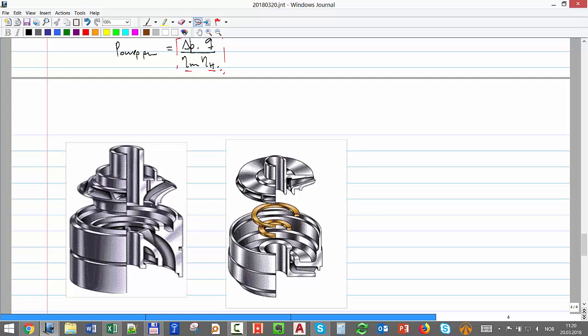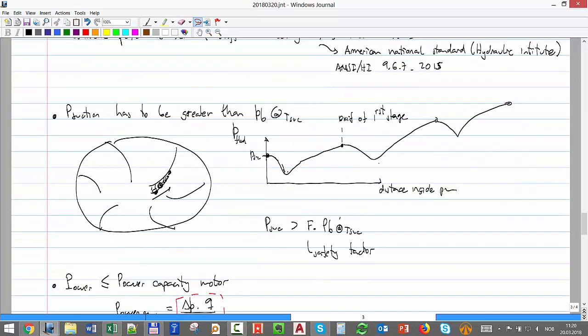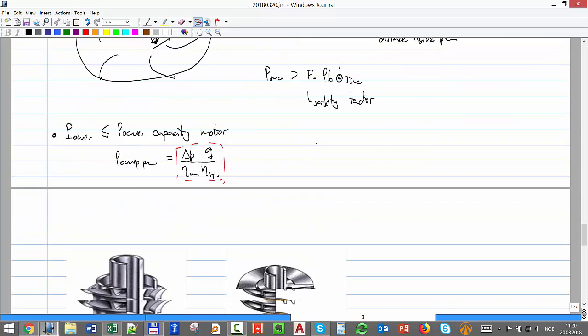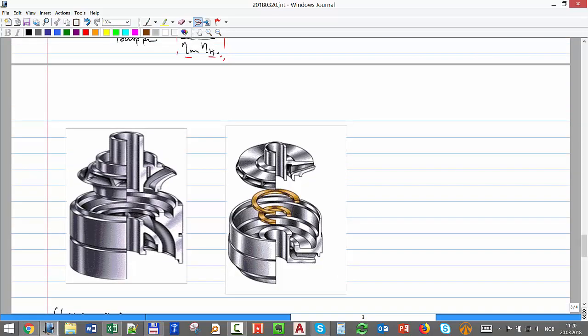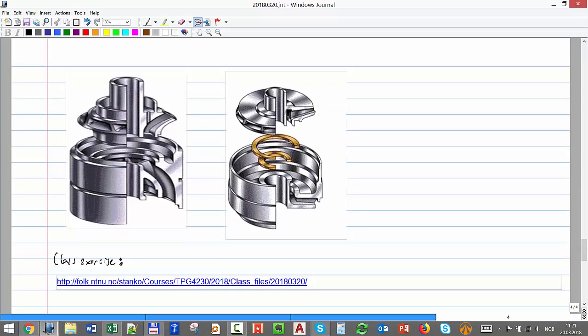So if you have a high gas fraction, we were saying 10%, 20%, not much, then you use this design that gives you less delta P, so you need more stages, but it's more tolerant to gas. Also remember the pressure is going to increase, so maybe gas will be driven back into solution after some stages. So maybe the first stages will be like that, and the other ones can be like this. Keep it in mind. It's like a gas tolerant ESP.